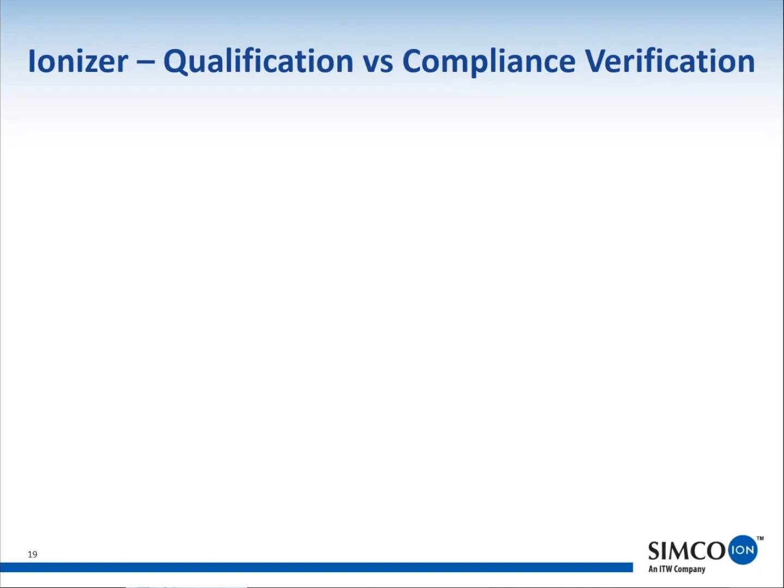Carl, excuse me. This is Tim. I have one more question. This is a write-in. The question is, which technology is more effective for plastic type and fiber type? Example, Tyvek insulators. Either technology works. Even though we manufacture the ions differently, you're just making an air ion. What you want to do is get that ion to the location as quickly as possible before it has a chance to recombine. So there really isn't a better technology for a particular type of charged insulator. Either one will work. Good question.